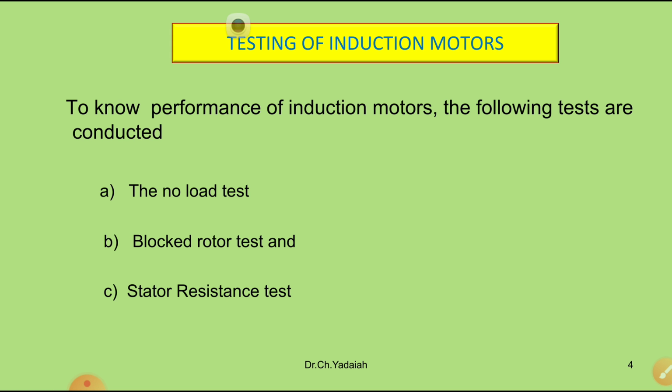What we found in the no load test on a single phase transformer: we gave the rated voltage to the primary side with the secondary side open circuited.